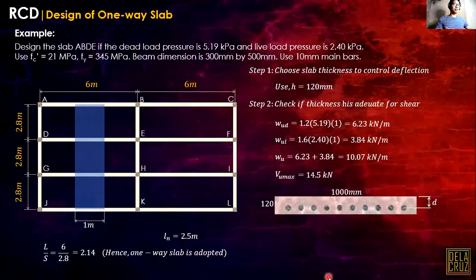Okay, so how can we calculate that effective depth? Okay, so we need to assume a concrete cover. So in this case, the minimum concrete cover for a slab, or concrete not exposed to the weather. So the slab is inside. Okay, that is 20 mm. This is the minimum concrete cover. It is in the code. I want you to read the code. We should be more code-based so that our assumptions are exact.